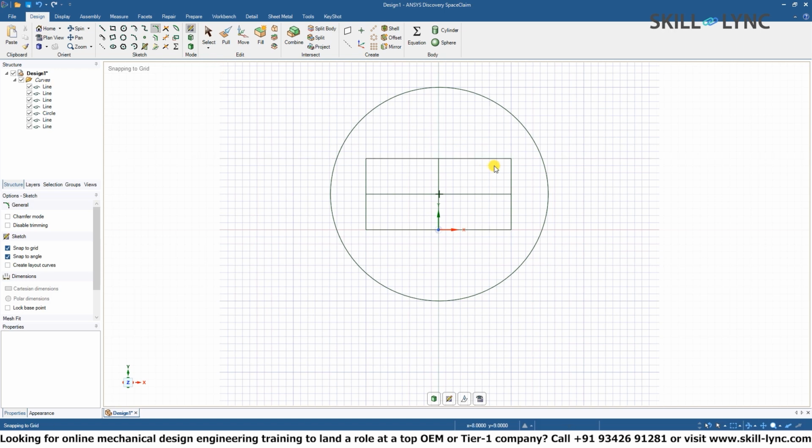What you need to do is select two lines, as an example, this line and this line. And as you can see, the preview already gives you an arc depending on where you'd like to connect it. So if we'd like to round off the corners of our rectangle, you can easily click on the two corners and it will create a rounded arc. You can edit the dimensions as discussed previously to suit your needs.